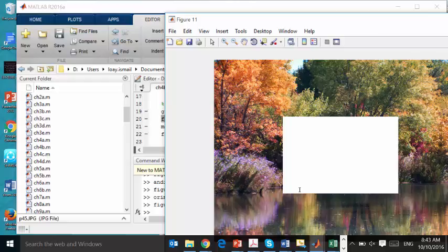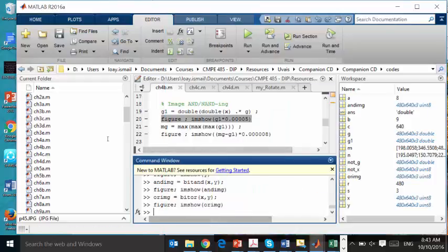Here I have something like this. Let's say that I want to compute X exclusive OR Y. This is equal to X prime ANDed with Y, OR with X ANDed with Y prime. Okay? So here we will write this equation. Let's put it something like this. Here I have the XOR image equal to.